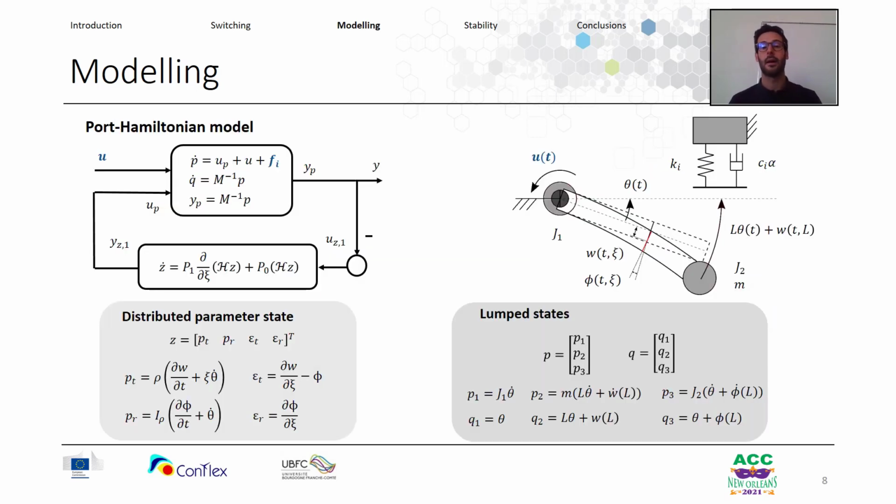Then the Port-Hamiltonian model of the rotating flexible beam that enters in contact with the external environment is composed by the power-preserving interconnection of a finite-dimensional Port-Hamiltonian system with an infinite-dimensional Port-Hamiltonian system. In particular, we remark that the impact force only affects the finite-dimensional dynamic, as well as the input.